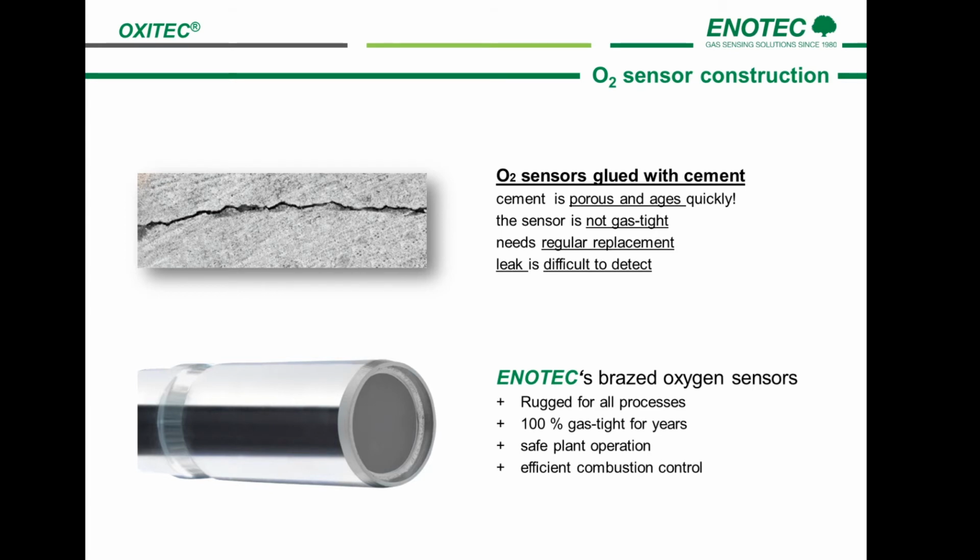Detecting a leaking sensor is difficult. When applying calibration gas to the sensor, the calibration gas displaces the leak air due to the higher flow rate of test air. The measured value will thus be seemingly correct, when in fact this is not the case.